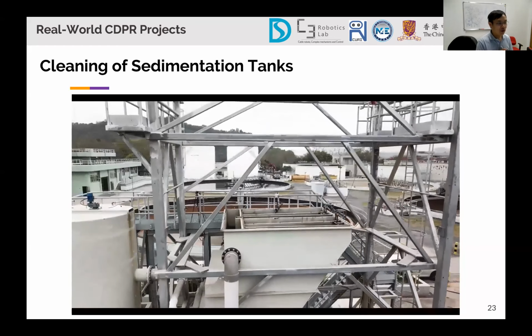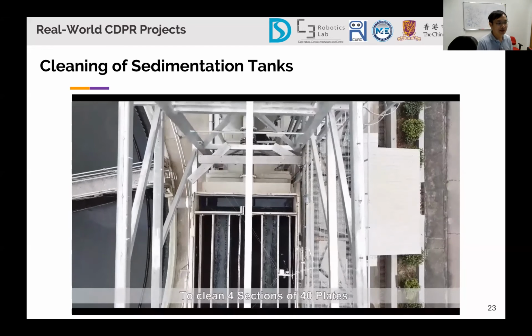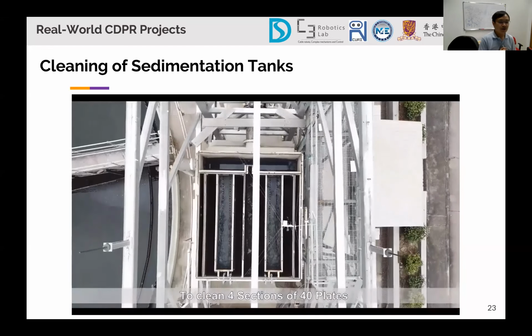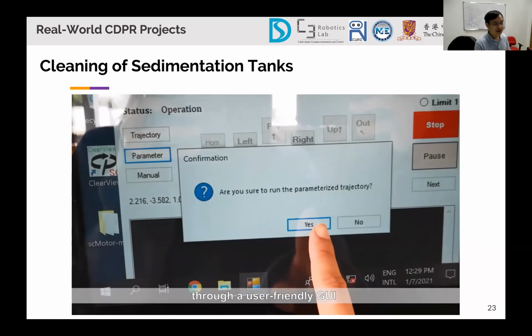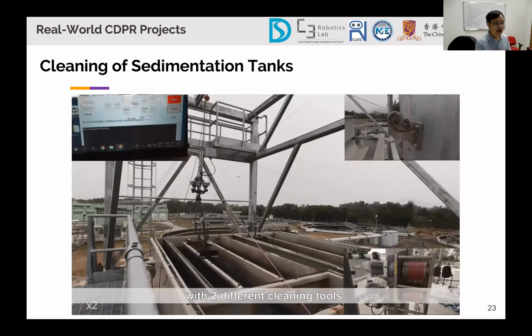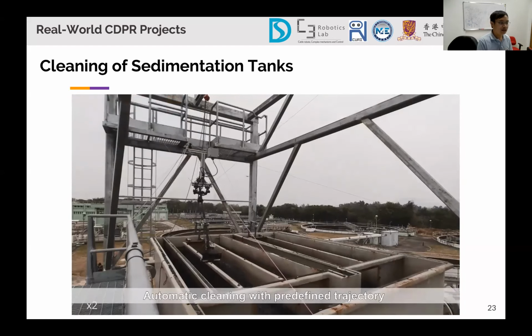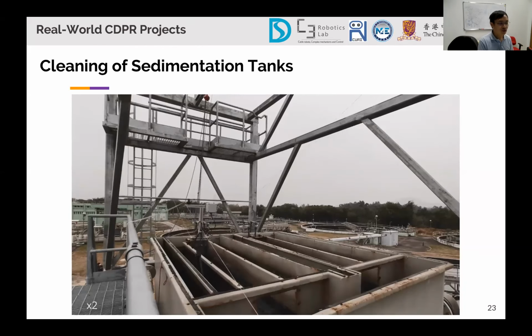So we developed a cable robot on a fairly, I'd say, massive frame. The frame is about 9 meters off the ground. And then we placed a cable robot, a fully constrained 8-cable cable robot, in there. We needed to move it from a prototype into something more mature. It could be out in the open, with rain, thunderstorms, typhoons. We set up the cable robot there for about 8 months to a year. So it withstood all of those annoying issues of weather.